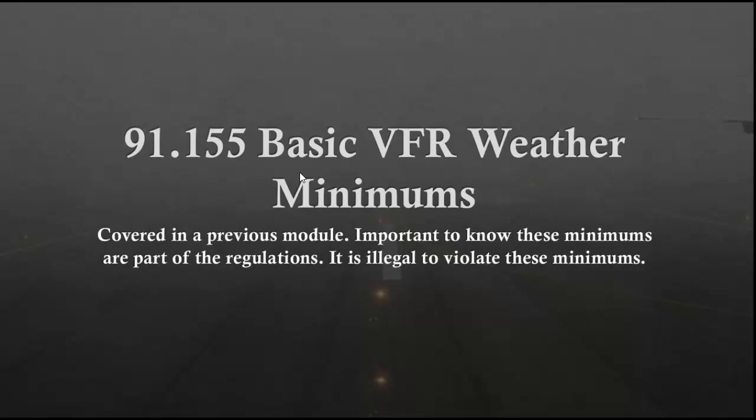As a VFR pilot flying around Murfreesboro, more often than not you'll be flying in Class Echo airspace. And the VFR minimums in Class Echo airspace at the altitudes you'll be flying at in the Diamond DA-40 or any other general aviation aircraft are at least a 3 statute mile visibility and clearance from clouds at least 500 feet below, 1,000 feet above, and 2,000 feet horizontal.